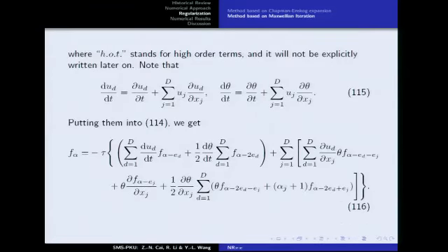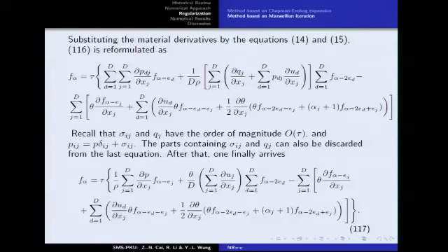and then we can substitute the Navier-Stokes-Fourier equation back into this part, and at last it tells us that some of the terms in this expression are still of high order, since the heat flux and the stress tensor are of order tau.